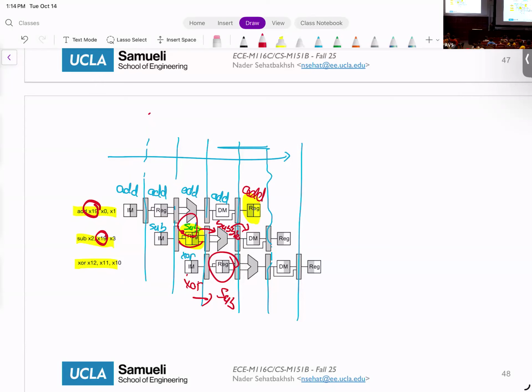So the question is, why are we not putting the bubbles in ahead of time? The answer is, if it's an offline phase at the compiler stage, you can do that, okay? But this is hardware, right? So the hardware does not know the future. It sees the sub and says, oh, we have a problem, so we insert the bubble. The bubble is generated on the fly.